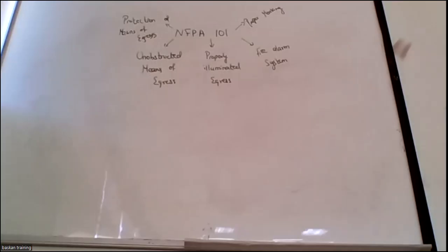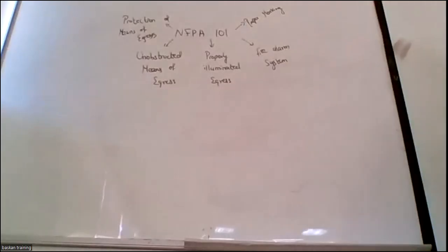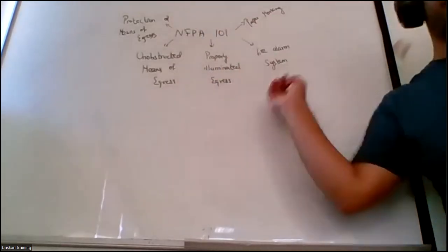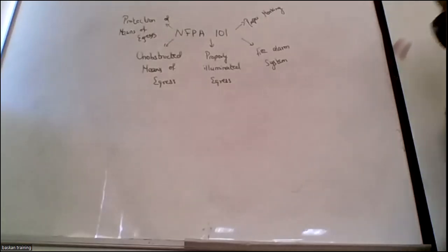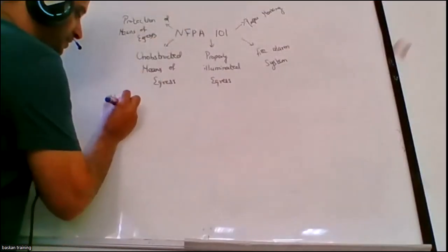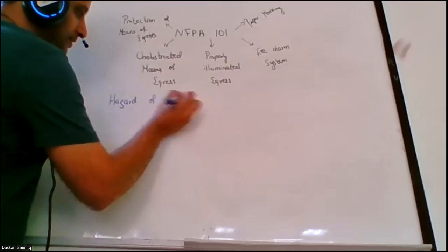But whenever we are talking about the basic requirements, NFPA 101 says that the first important parameter is the interior finishing. If your interior finishings are controlled, it means your flame spread index values will be controlled. If your interior finishes do not have flammable materials, flammable walls, flammable interiors, then these parameters will not be affected. So NFPA 101 says that the contents you are going to store within the occupancy can be categorized into three hazard of contents.